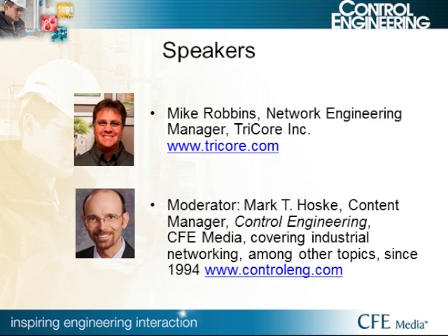So if you're using Ethernet IP on a network, you definitely want managed switches, and enable IGMP snooping on them. If you're using something like Modbus TCP, then you can use unmanaged switches if you want to. I would still recommend managed, but you can use unmanaged switches because it doesn't use multicast traffic. Profinet is another story. There are 3 different levels of that network, I believe, and which one you're using defines which switch you'll have to use.